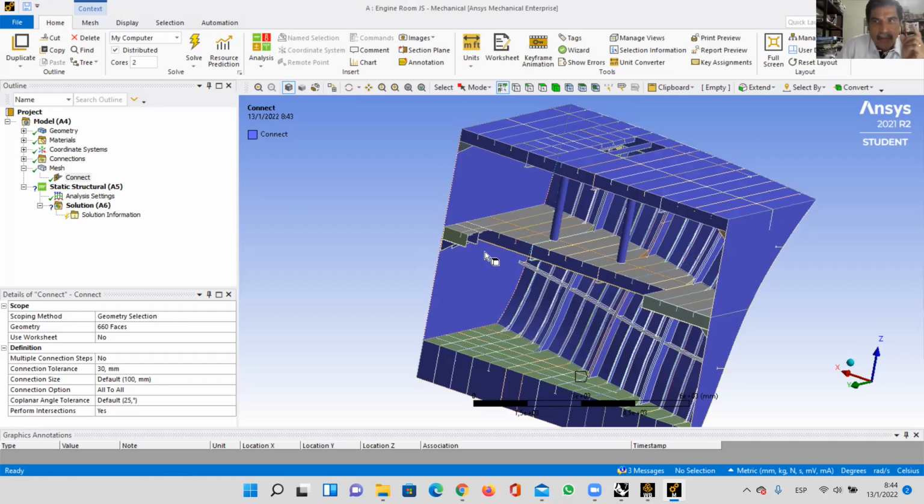Now, that's one. So you're going to consider the same weights, but with the original and with the corrosion effect, right? What we wanted to do is the static load, but analyzed in two cases for the corrosion part. We wanted to do the same analysis, but with this Lloyd rule, we want to analyze for the 30% of some elements and the 25% of corrosion allowance. Okay. The same structure. And then we are going to analyze the influence of the dynamic load, the wave load. We calculated and we got a load of 125.8.